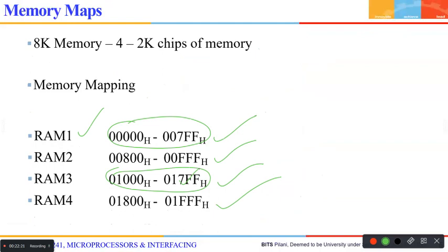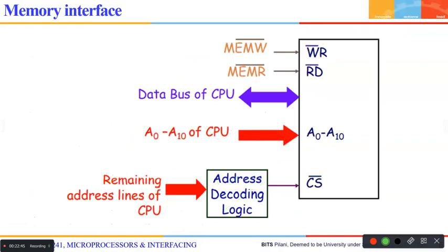Will you keep quiet? No, you will not keep quiet. Use a 3 to 8 decoder. Maybe four lines you are wasting, it doesn't matter. If it is asked in the question that you use only a 3 to 8 decoder, use only a 3 to 8 decoder. Understood this? This is a very important step. Everyone should understand this.